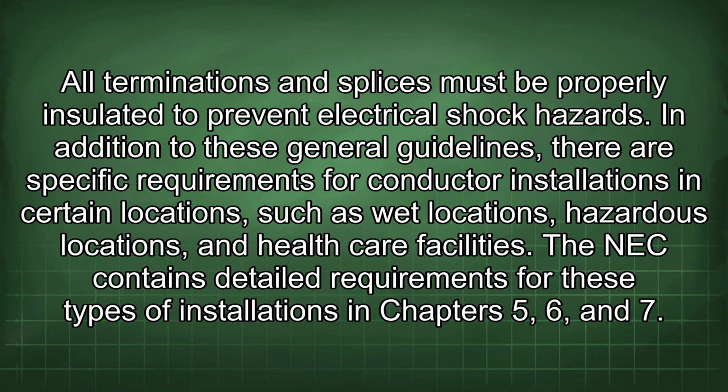All terminations and splices must be properly insulated to prevent electrical shock hazards. In addition to these general guidelines, there are specific requirements for conductor installations in certain locations, such as wet locations, hazardous locations, and healthcare facilities. The NEC contains detailed requirements for these types of installations in Chapters 5, 6, and 7.